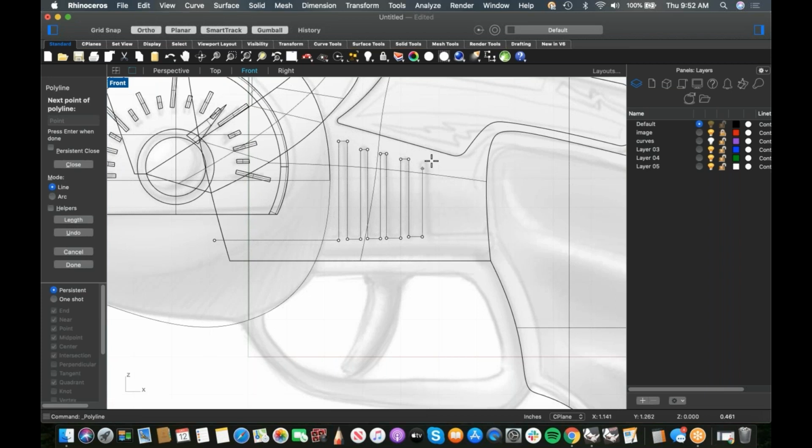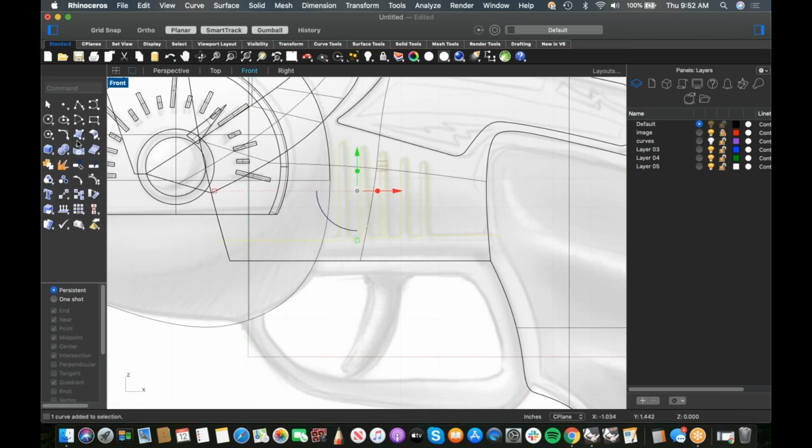And there's a couple of cheats that we can do. Watch this. If I was really sloppy and didn't line any of these points up, which I didn't, see how none of these line up? Check this out. If I grab all of this, gumball pops up. If I click this and hit 0, boop, they all line up again. Hooray!